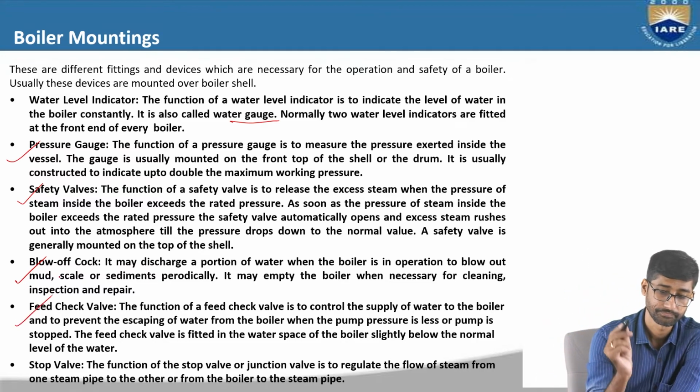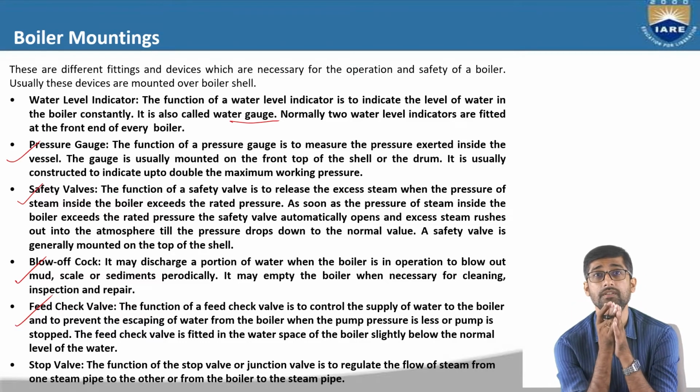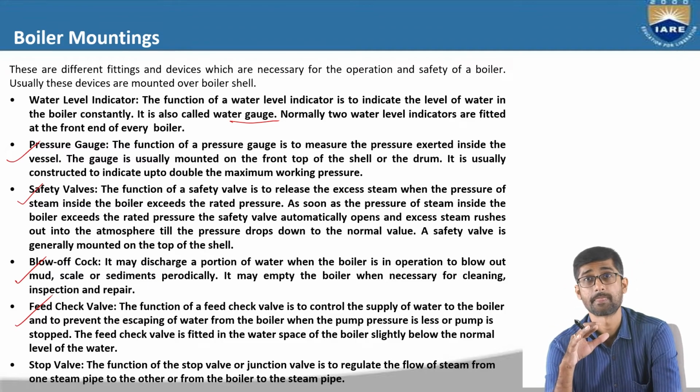Next, feed check valve. The function of this feed check valve is to control the supply of water to the boiler and to prevent the escaping of water from the boiler when the pump pressure is less or the pump is stopped. The feed check valve is fitted in the water space of the boiler slightly below the normal level of the water.